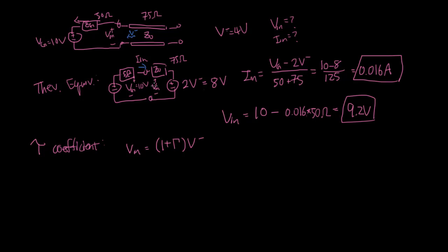The other subtle thing to remember is you have this negative wave going in, but you also have that initial positive wave. If we go back to the bounce diagram, remember you had a wave going out and a wave coming in. This voltage here is actually not just B, but A plus B, when you're calculating the voltage at this point.